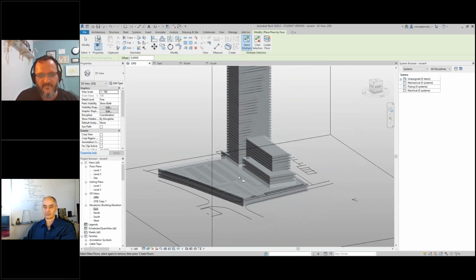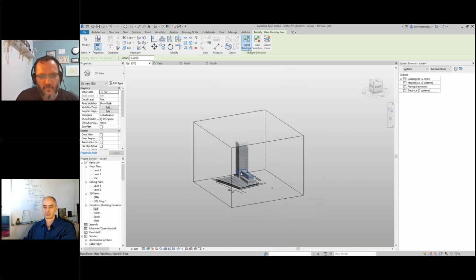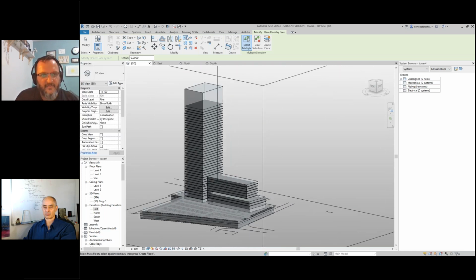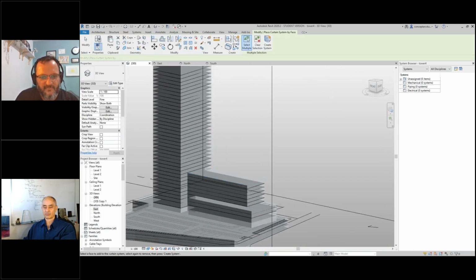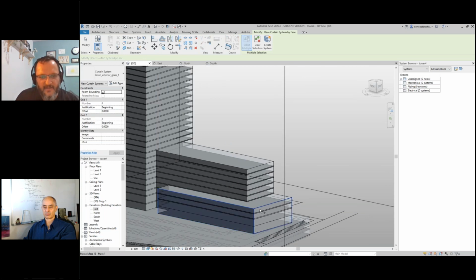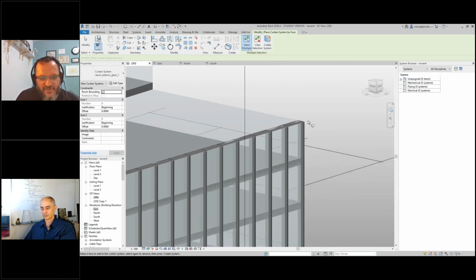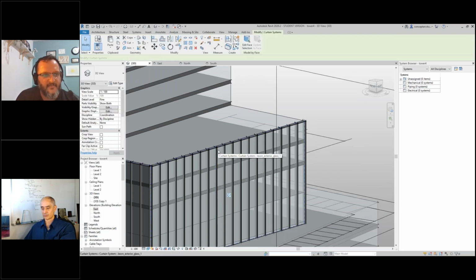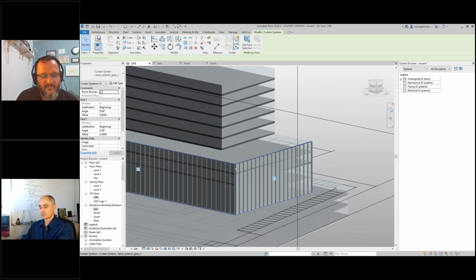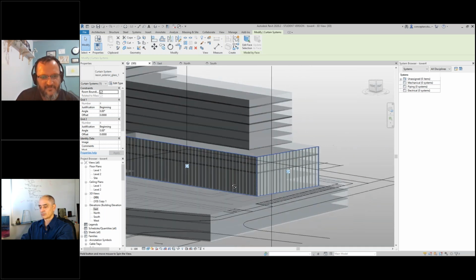I'm just going to show you the wall system. It's going to take me about 2 minutes to show you the wall systems. So basically in Revit, we have curtain wall systems, which are unbelievable. They allow us to create mullions and glass. I'm going to add it to these two surfaces over here, and you can take a look. This is glass and 4 mullions. I can adjust the sizes easily. There's a selection tool here on the left, which will allow me to place as many as I want, horizontally, vertically, like a grid structure.